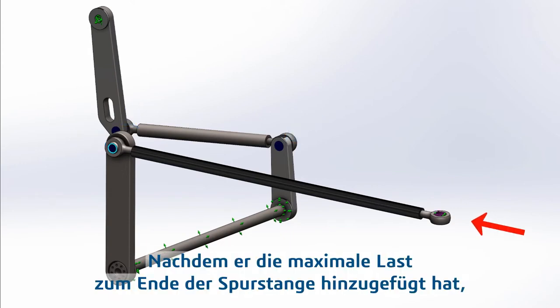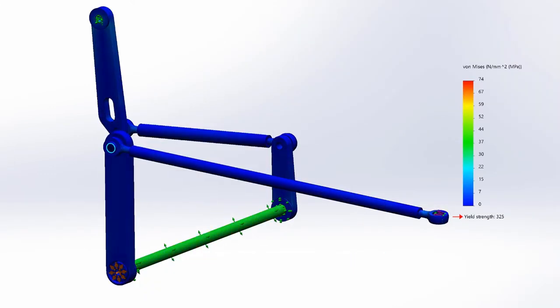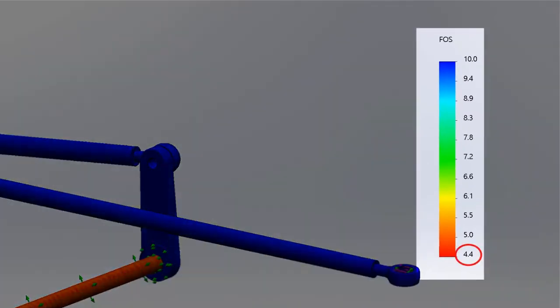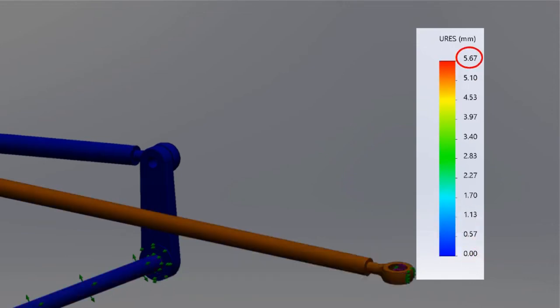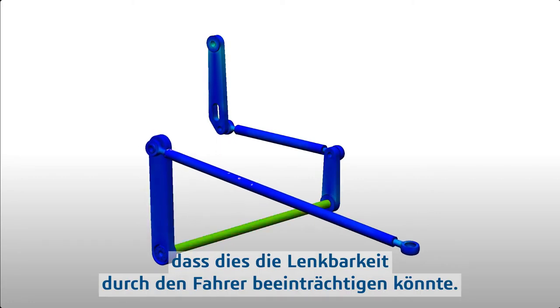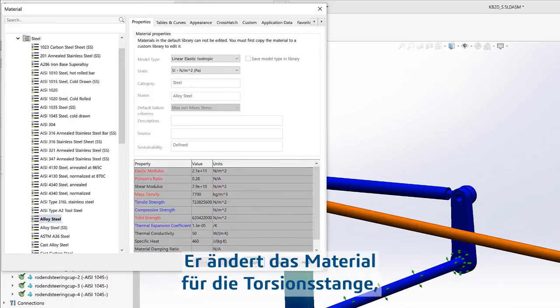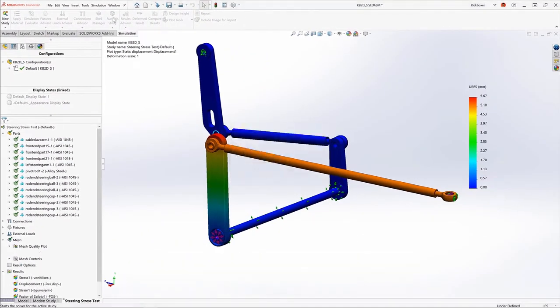After adding the maximum load to the tie rod end, he runs the analysis and views the results. He can quickly see that the system passes the factor of safety test, and then checks the maximum displacement just in case. It appears the torsion rod is twisting so much, it could affect the rider's ability to control steering. He changes the material of the torsion rod to something a little stiffer and reruns the analysis.